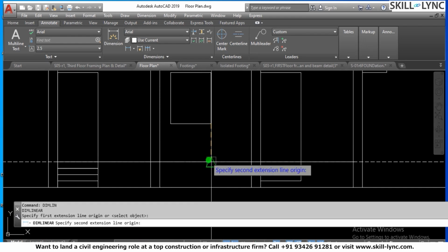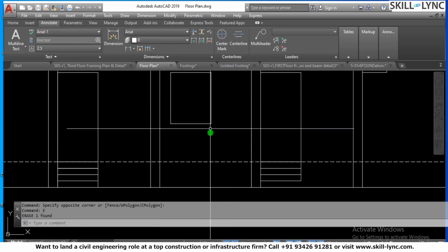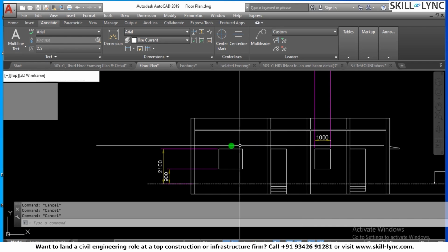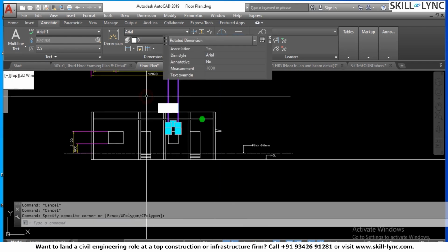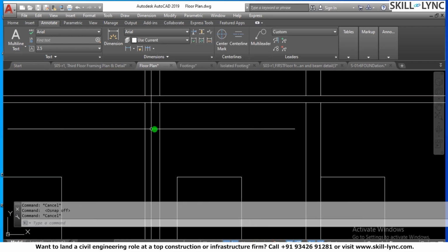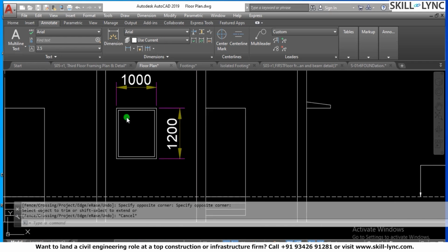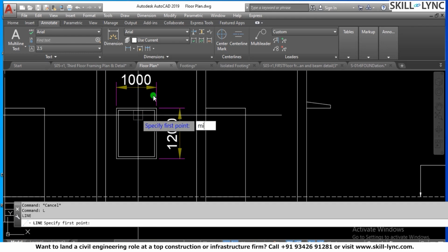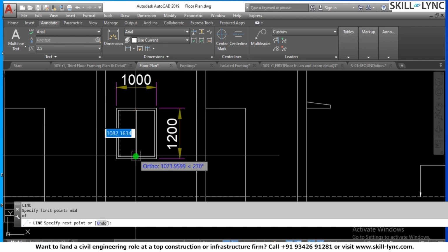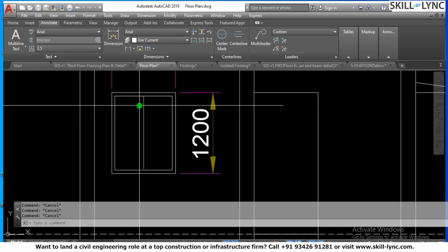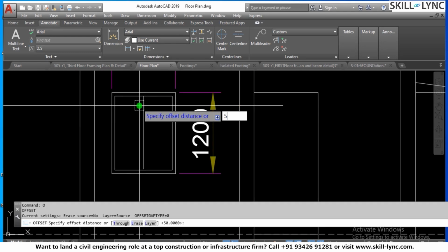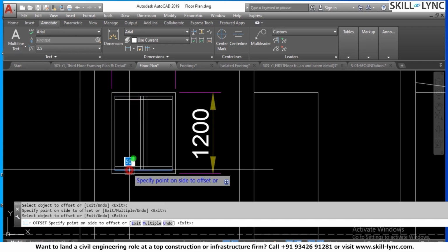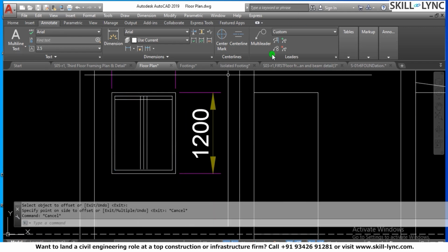If I want to reduce the size, you can see that the extension line size is increasing a lot because of the snapping point, so right now I put the snap off. Then I can have dim limb. You can see that the frames are created. Then we can have the panels of the window over here. I take a midpoint from here. If it is a double window, I can have, let's say, a 50 mm panel with glazing. This is just one sample of the window that you are seeing over here.